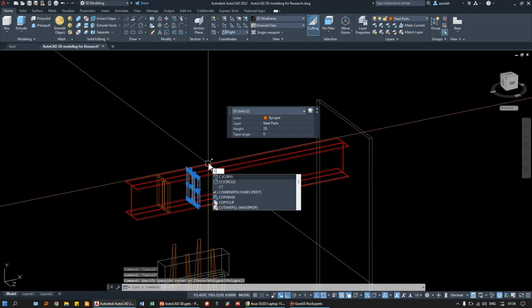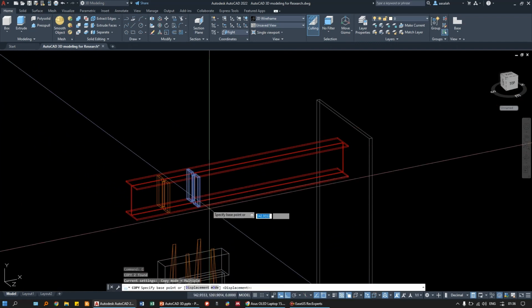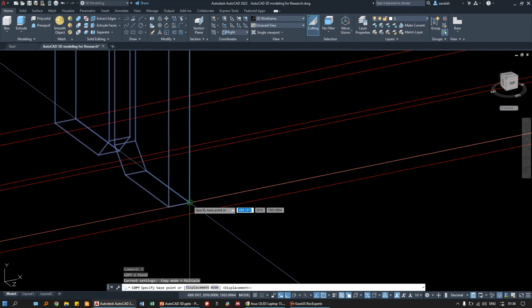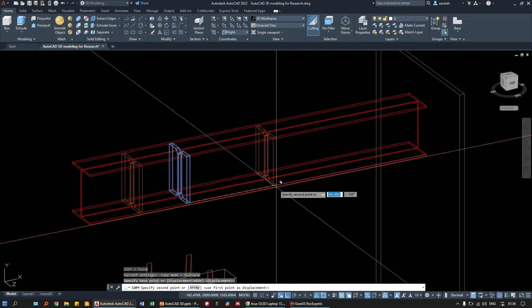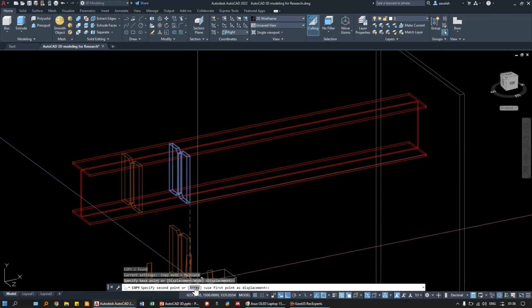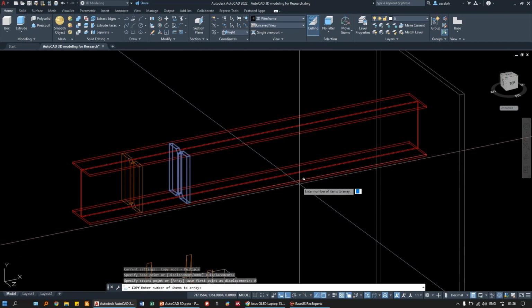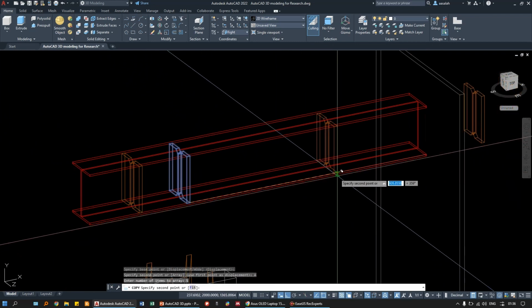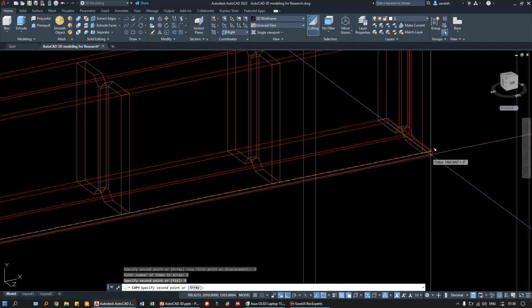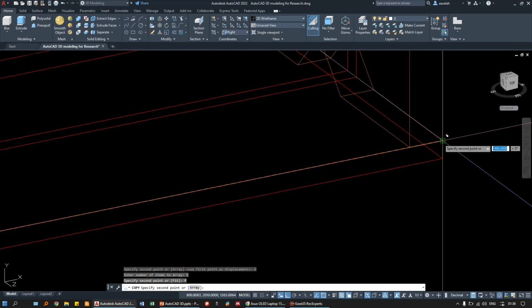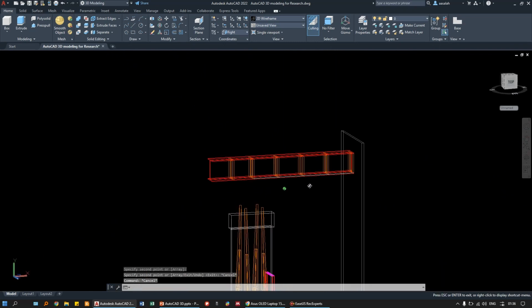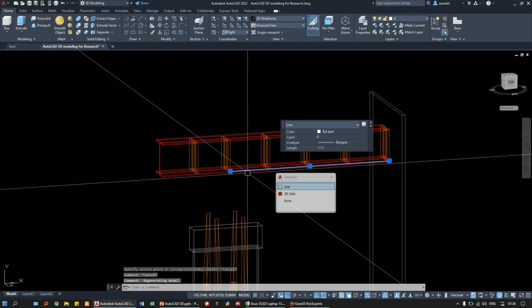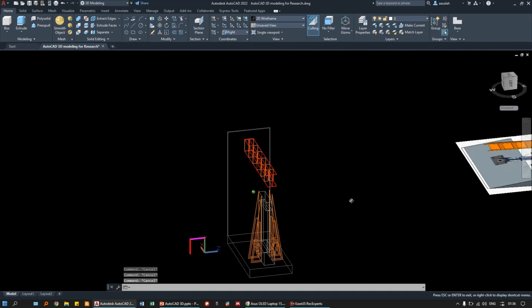So when I copy, I start selecting the point where to hold this stiffener, and then I click on array, how many, I need 5 for example, and fit into the line that I have already put here. So now we have the stiffeners that I need. We can do more, 5 aren't enough, but that's enough for now.